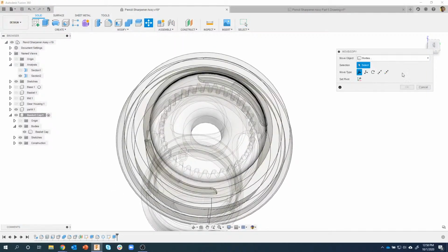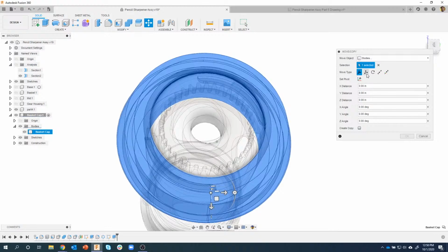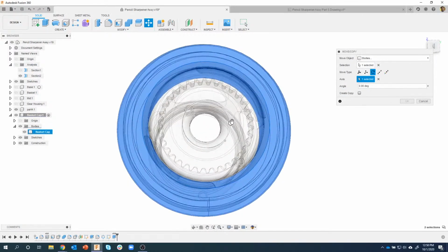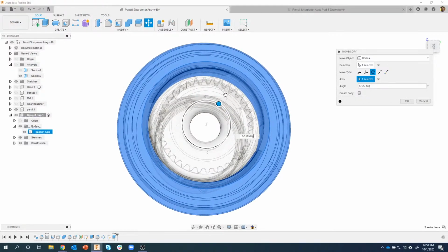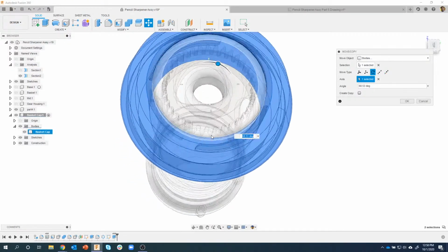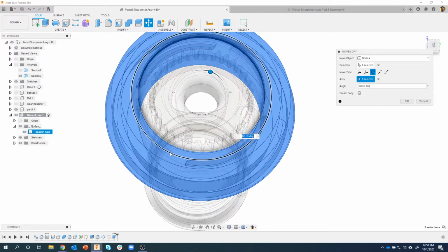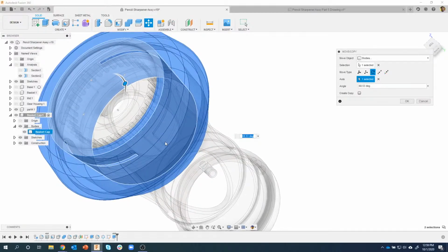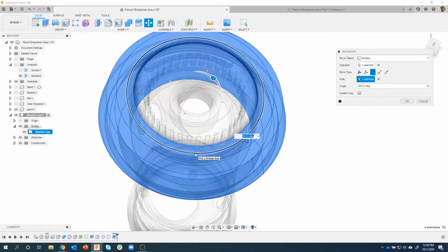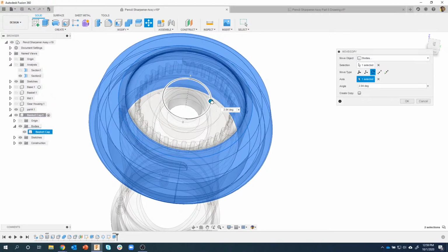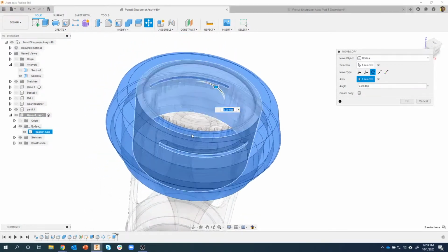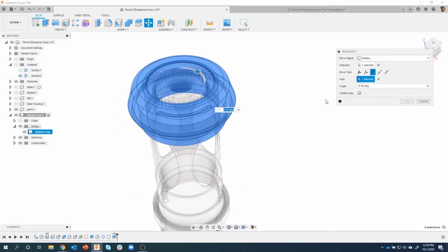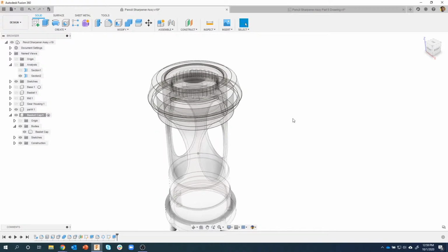I'm going to move this part, and let's do a rotate around the axis. We should be able to see that thread. As I rotate this around, we can see, sure enough, that thread is rotating, and we have clearance past that L and clearance before we hit that L over there. So you would basically drop this cap down and then rotate it into place, and that's how it gets held into place. And we used the information from this other part to help us design the cap.